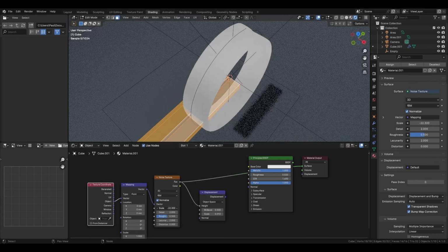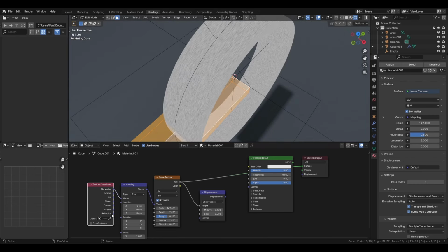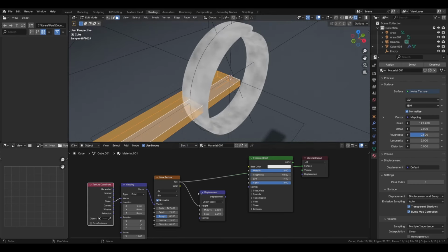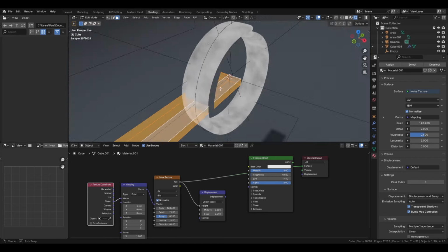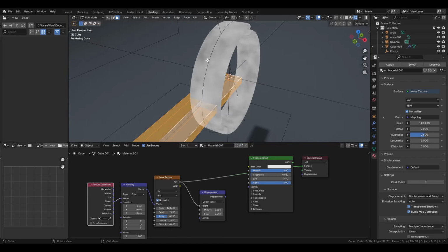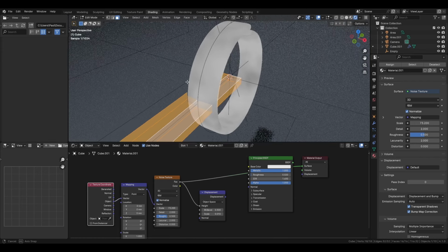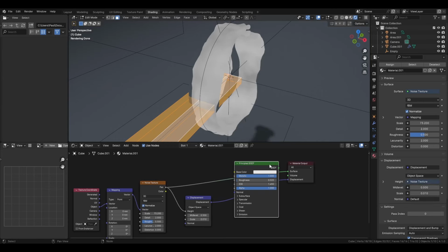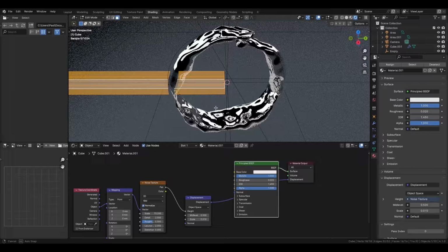Sometimes, well, it seems too great. Yeah, actually you can put object. I don't think it's correct to put object, but it's better than the generated one and better than the UV. So just keep object, and you see the sort of noise created. Just don't make it too low, so something like this maybe. And then use this for the height as you did, and then displacement, and then Control Shift on the Principled BSDF to come back on the thing.